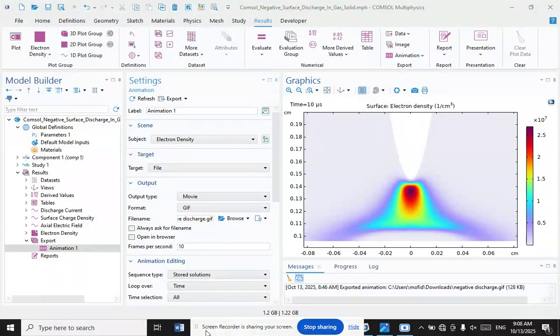The device is driven in a linear motion along the length of the panel, thanks to the ionic wind generated on the surface of the panel. The moving device carries the dust along the longitudinal direction of the inclined panel. This motion of the device, like a broom, enables contactless cleaning of the panel surface. Upon reaching the end of the panel, the device is driven upward again to return to its initial position, and it can then be activated to perform a second pass and remove the remaining dust.